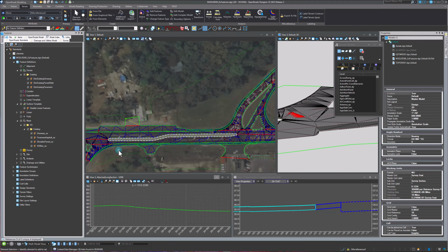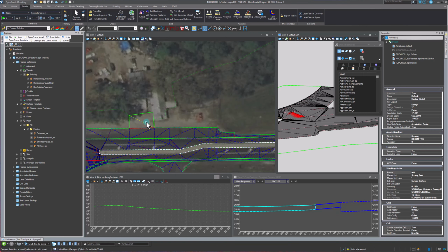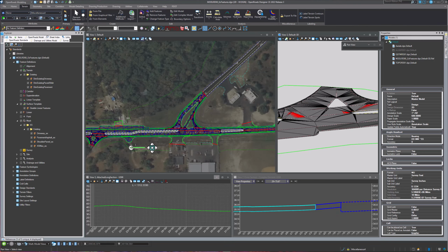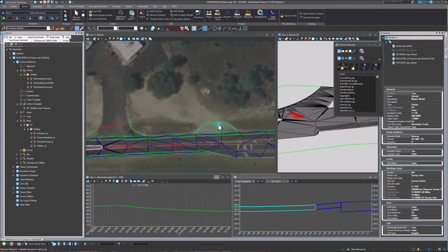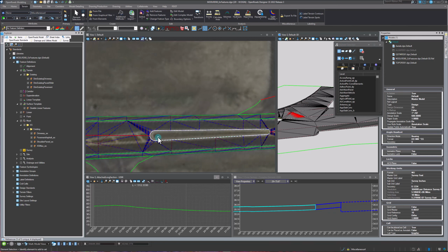So we've done 3 different types of turnouts. Essentially, we've got your asphalt turnout. We've got some asphalt over here, but then we also showed how to use excess miscellaneous when there's something like dirt. And we know that this dirt doesn't have a volume option, so it won't affect earthwork, I should say. And then we used the concrete driveway option over here. All right, next let's get into making some curb.